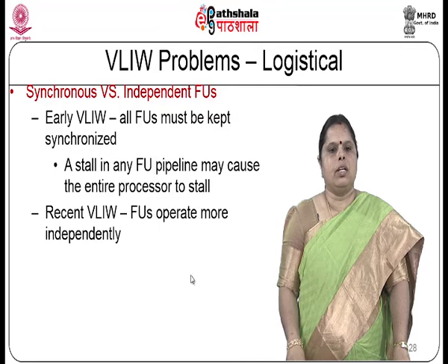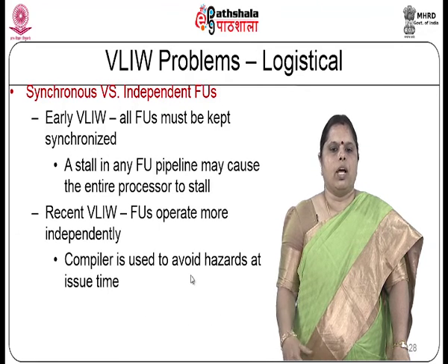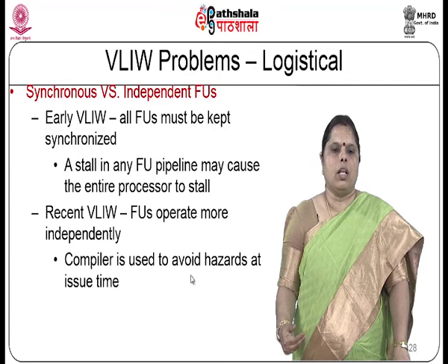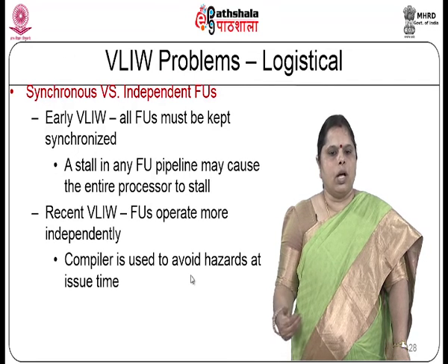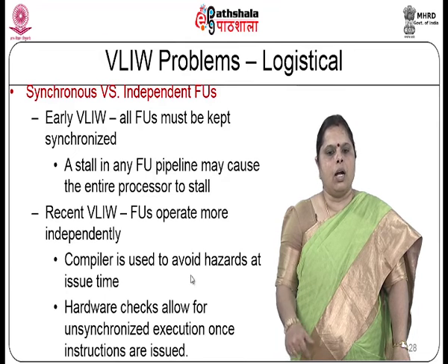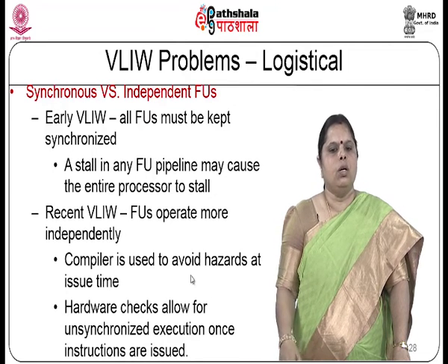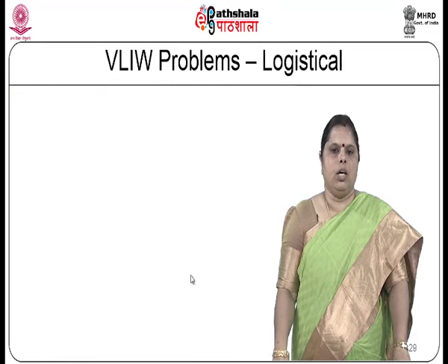Now, these days of course, the recent VLIW processors do some amount of dynamic scheduling also, where the functional units operate a little more independently. So, the compiler is used to avoid hazards at the issue time, but the hardware checks allow for unsynchronized execution once the instructions are issued into the hardware.